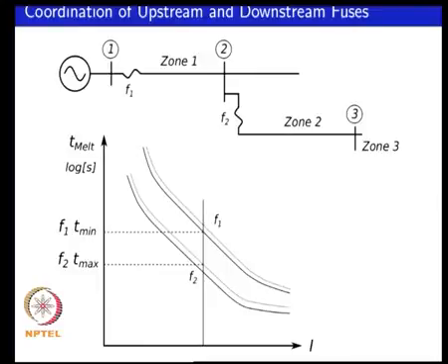In the case of a circuit breaker you have the pickup current and the actual current flowing through the protective device. In the case of a fuse, you are looking at a ratio between your actual current flowing through the fuse and the current required to melt the fuse. Okay. So, similar to what we defined for the circuit breaker, you could now define a ratio M,